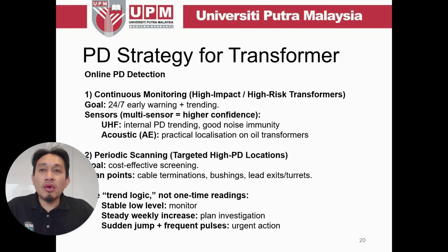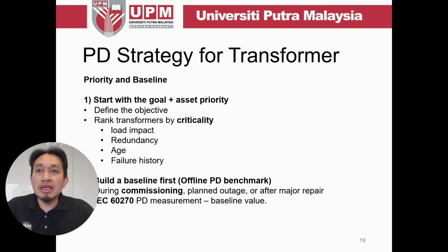Once we have the baseline value, we can set monitoring on a specific frequency basis. That frequency is determined by the criticality of the transformer itself. If the transformer is highly critical, the frequency can be much more frequent, maybe every 2 years.